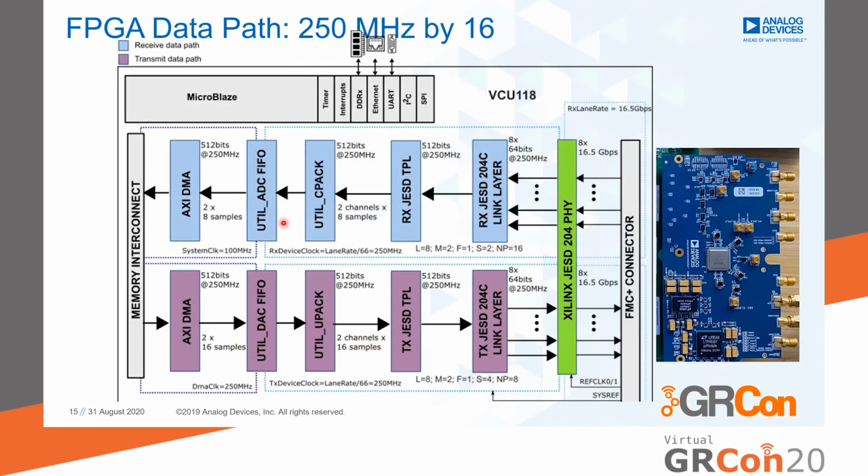Now, if we transition over to the 9081, things are a bit different. You can see first of all that there's a lot more IP cores inside the FPGA. But one of the main differences, if we start off at the FMC card, is that the interface is much, much faster. So this is actually using JESD204B or C, depending on the mode that you're using. And that's a JEDEC standard where we can generate a high-speed link to the device instead of having many, many LVDS lanes.